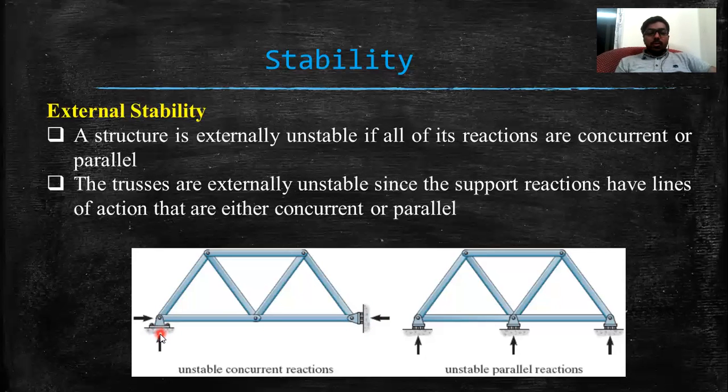So when movement in both the horizontal and vertical directions is restrained, we will get two reaction forces, one in the vertical direction and another in the horizontal direction. But we will not get any moment here, because the hinged joint allows rotation. So there will be no moment at this joint, as well as in the case of the roller.